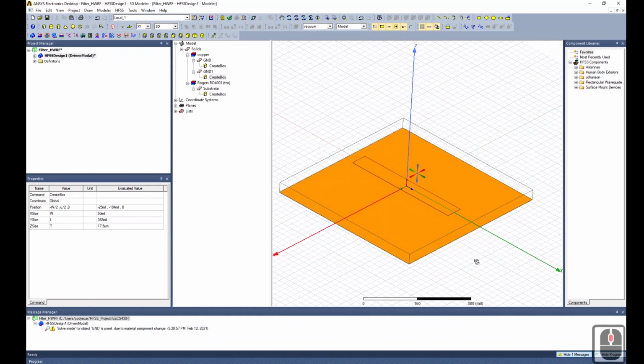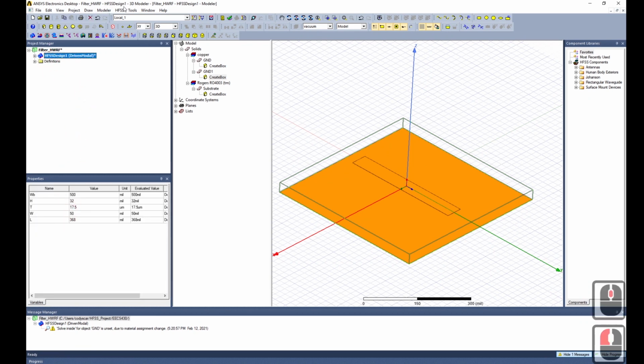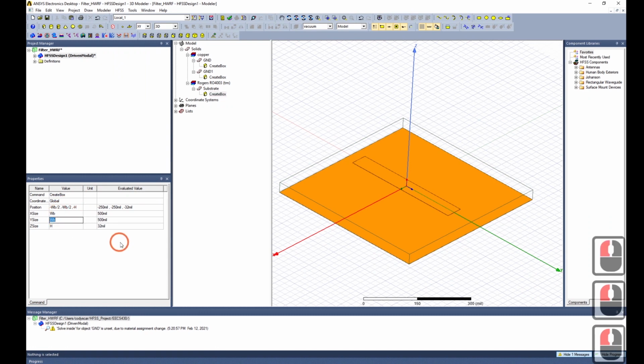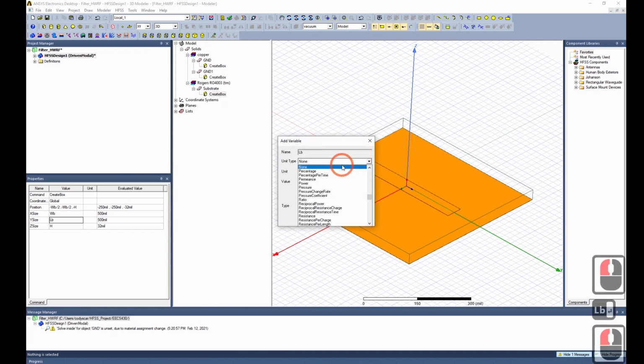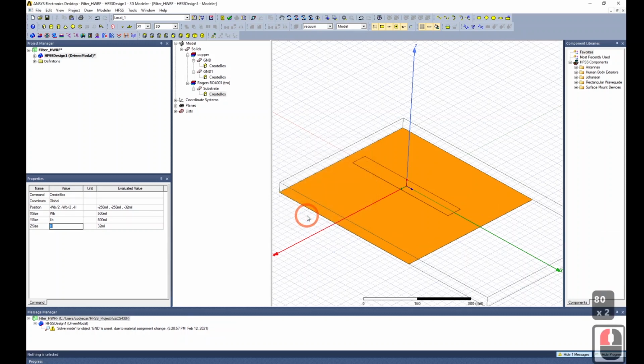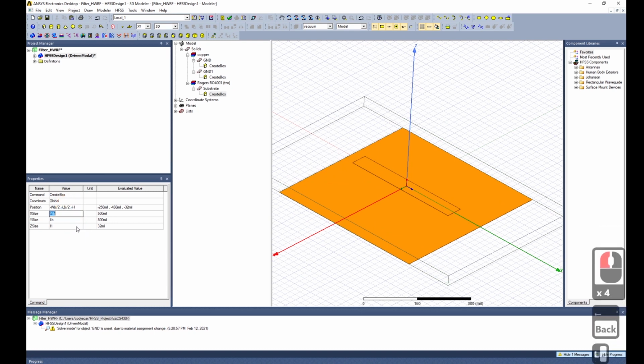So I'll probably go ahead and add in a length for this box. So let's, for the substrate box, here we go. Let's go into our substrate. And instead of Y being WB, let's make it LB. Call it a length. And we'll make it, let's see, maybe 800 mil. Okay, yeah, minus LB over 2. Awesome. And same thing for the ground plane.